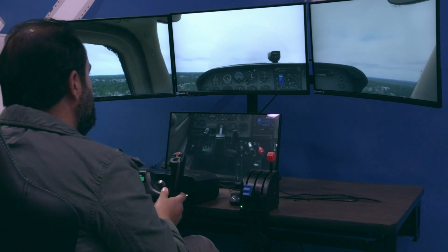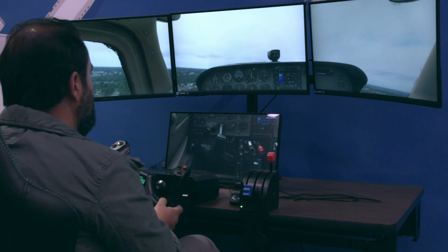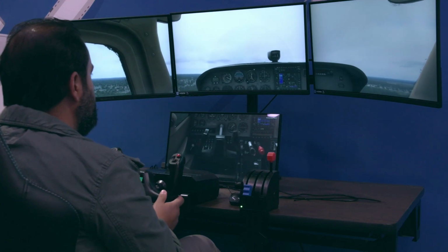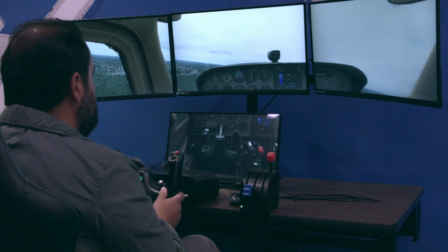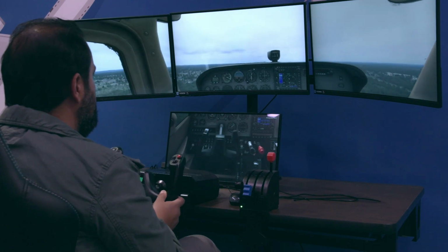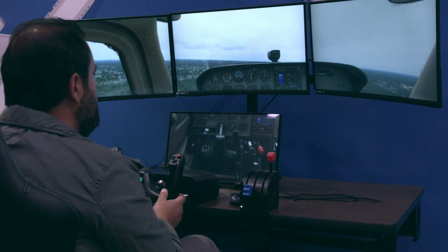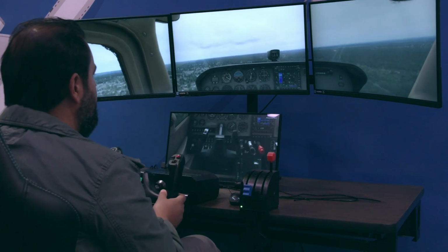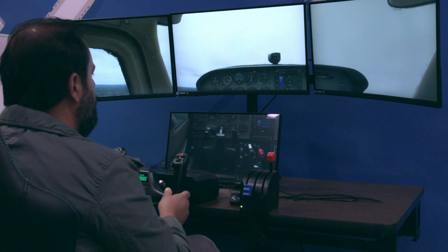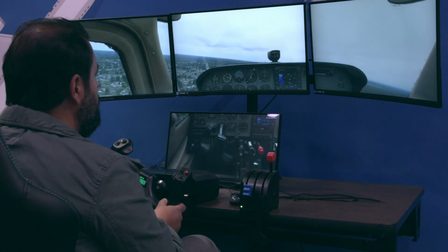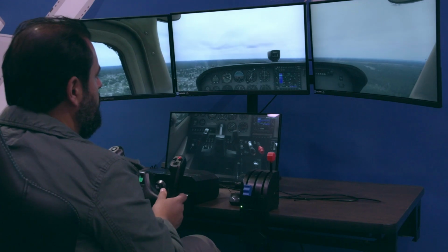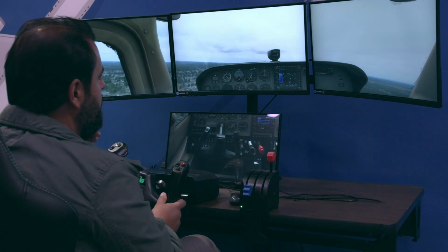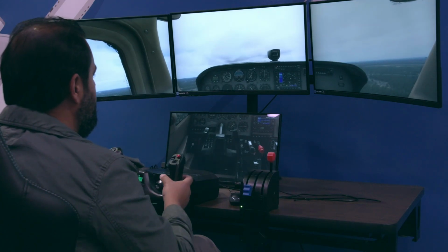You want to make sure you actually maintain your altitude as much as possible and your pitch, and then you are going to change the angle of attack by scenarios, pitch up, pitch down scenarios, so you have enough data for your aircraft. And I want you to make sure you reach the stall condition. So I want you to break this flight, so you can give me a comprehensive lift coefficient versus angle of attack.